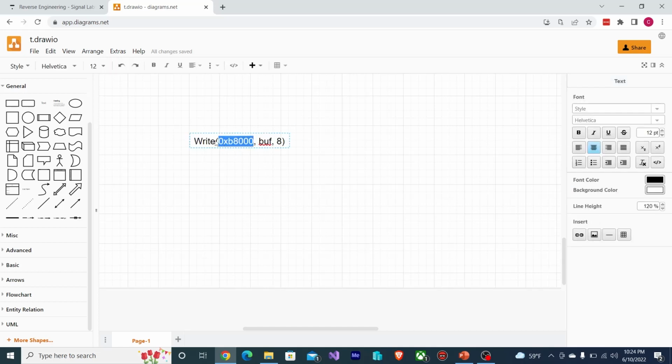If this is the actual physical address it's writing to, on x86 systems that's going to go to the VGA controller. That's not going to go to RAM or in memory. The CPU is going to see this address and know that it corresponds to hardware, and it's going to pass the write through to the actual hardware, right? In this case, it's VGA. It could be your graphics card, it could be your network card, things like that.